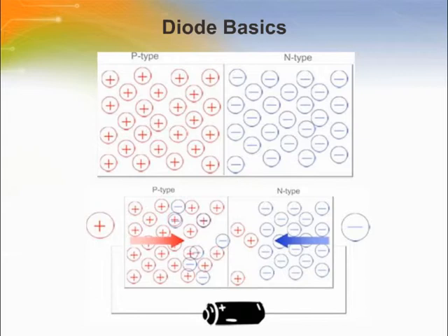When the N-type and P-type material are combined with no external charge, the free electrons in the N-type material move from the negatively charged area to the positively charged area, P-type, and the free electrons move from hole to hole. As electrons from the N-type material fill holes from the P-type material along the junction between the layers, they form a depletion region. In the depletion zone, the material becomes an insulator and there is no current flow.